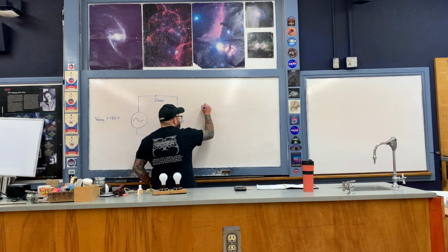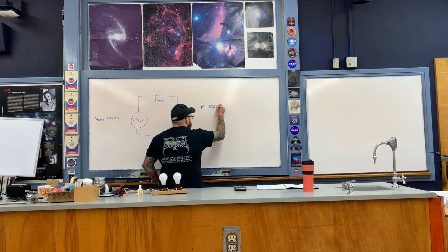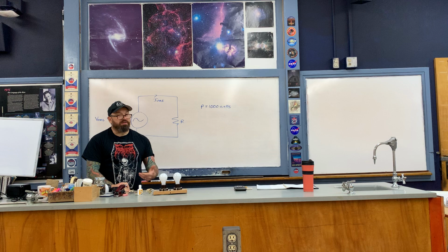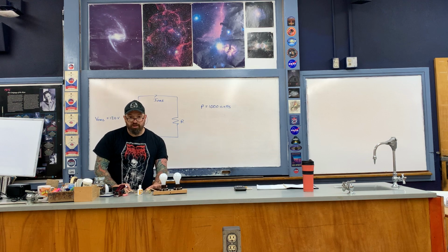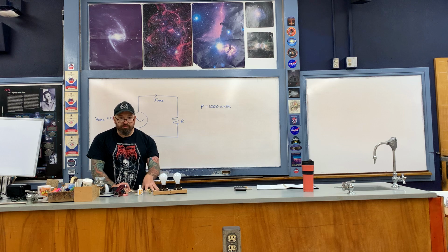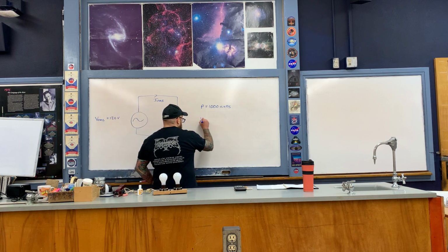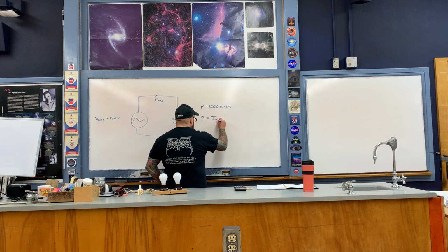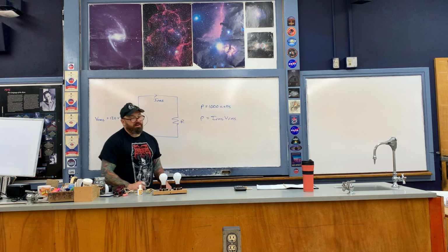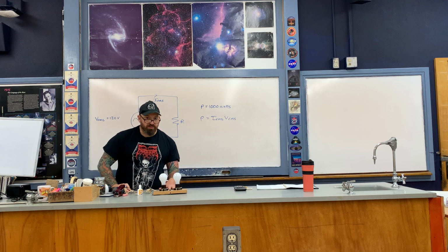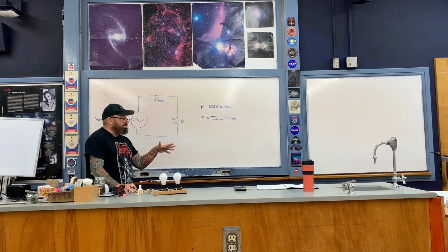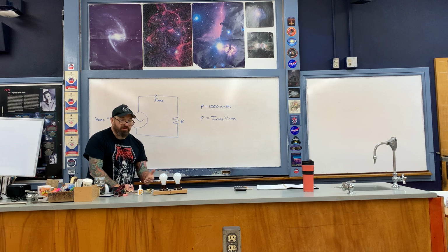Now the hairdryer itself operates at 1000 watts. In other words, that's the amount of energy per second that is being delivered to the hairdryer by the generator. So from part 1 of today's lectures, we can write down the expression: power equals I times V, where we have the RMS values for alternating current written in the expression. Now let's immediately calculate the amount of current, IRMS, that's flowing through the hairdryer.